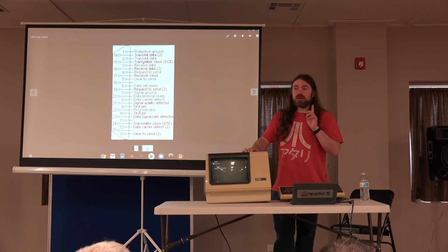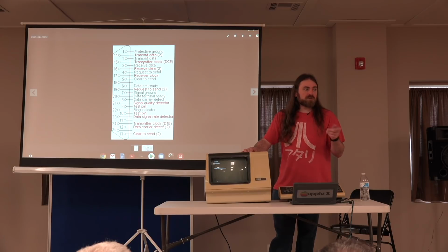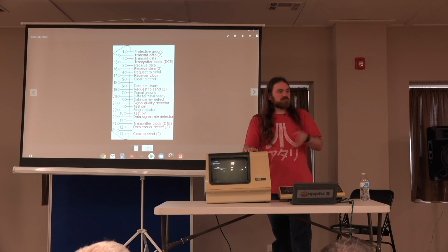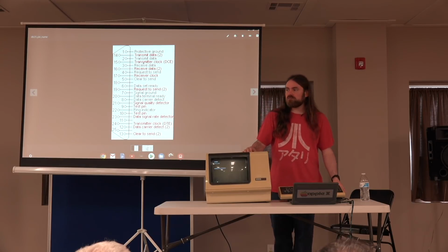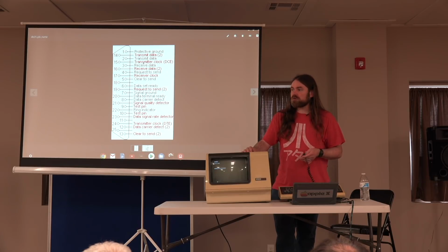The 240 is the same terminal base, it's just a different monitor. Because the VT240 can generate the color, you just need the color monitor, and that's a little bit hard to find. It's a 15 kilohertz RGB monitor with sync on green, so you can rig it up to other things if you don't have the correct monitor. Same thing with the DEC Rainbow, which isn't a terminal, it's a computer, but again you can rig up a regular monitor to that. And the same keyboards work across those DEC PCs? Correct, it's the same keyboard.